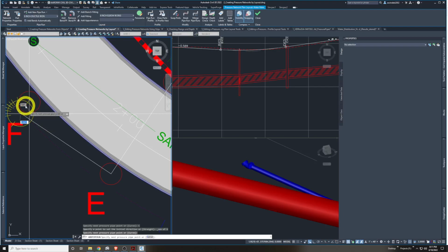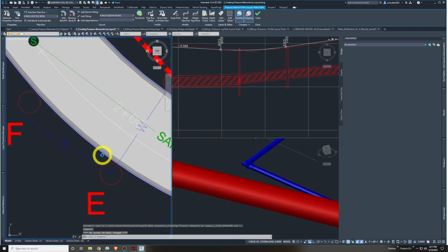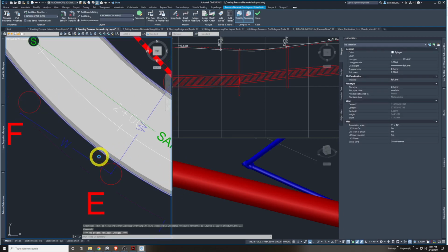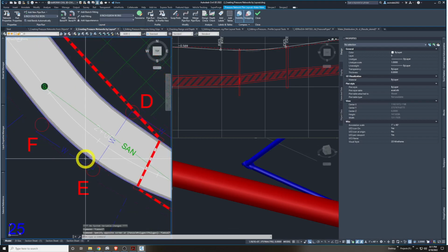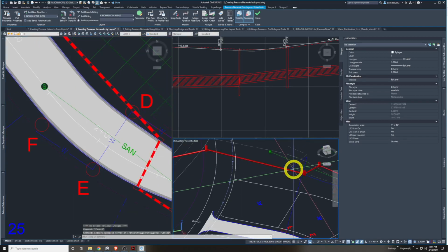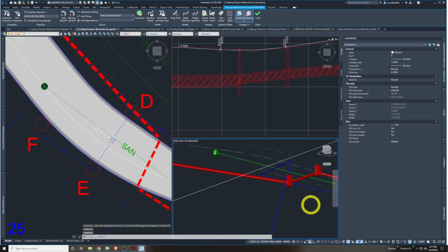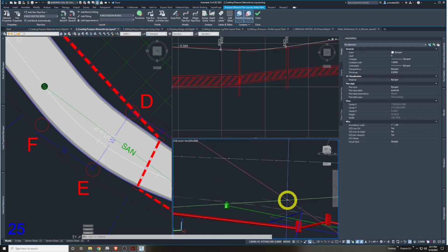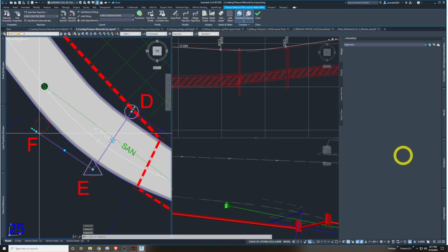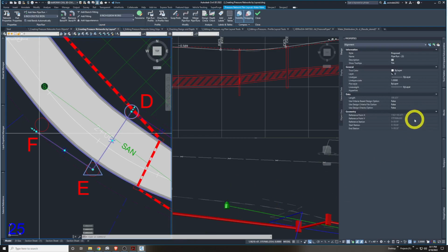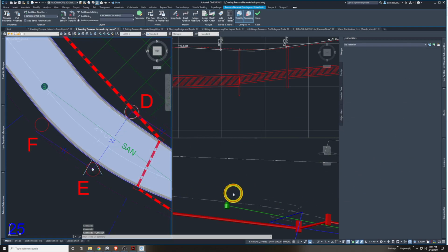And let's hit enter, let our pipe network create. A little off from the book because we have different commands that have come in over the years. So if I go back to here, let's rotate to a more favorable position to look at our pipe network. We can see it's now added. My last pick over here goes to elevation 0, which is not ideal. It shoots way down somewhere where we don't want it to.